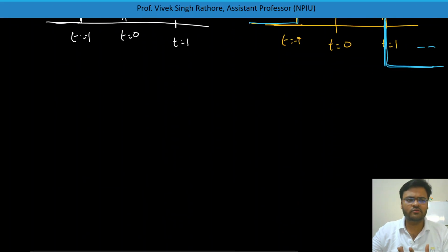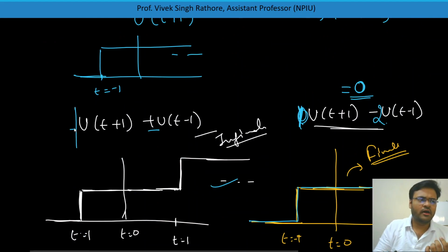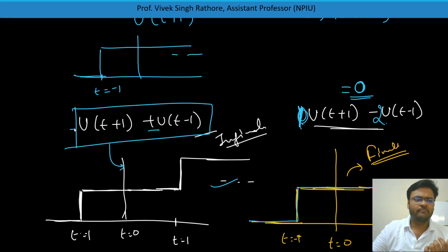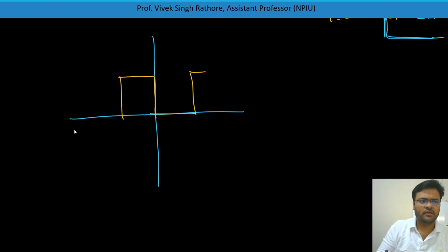From this question you have understood how to represent a signal if I give you the expression of unit steps; you can plot it like this. But if I give you the direct plot, can you write it in unit step signals? So let's see. First I'll give you this plot, and there is a graph like this. This is amplitude 1, this is amplitude, I think we'll say, -2, and this is the time axis: -1, 0, 1, 2 and 3.